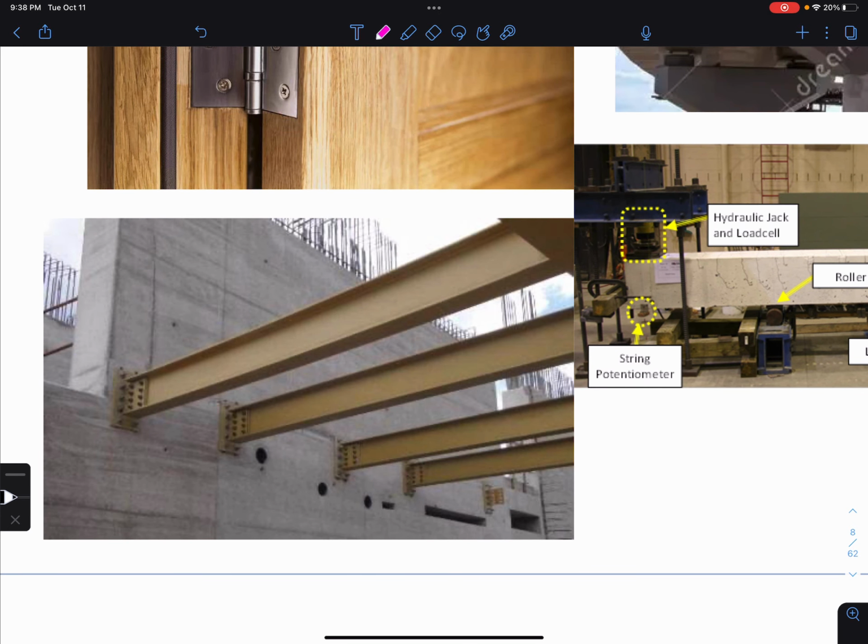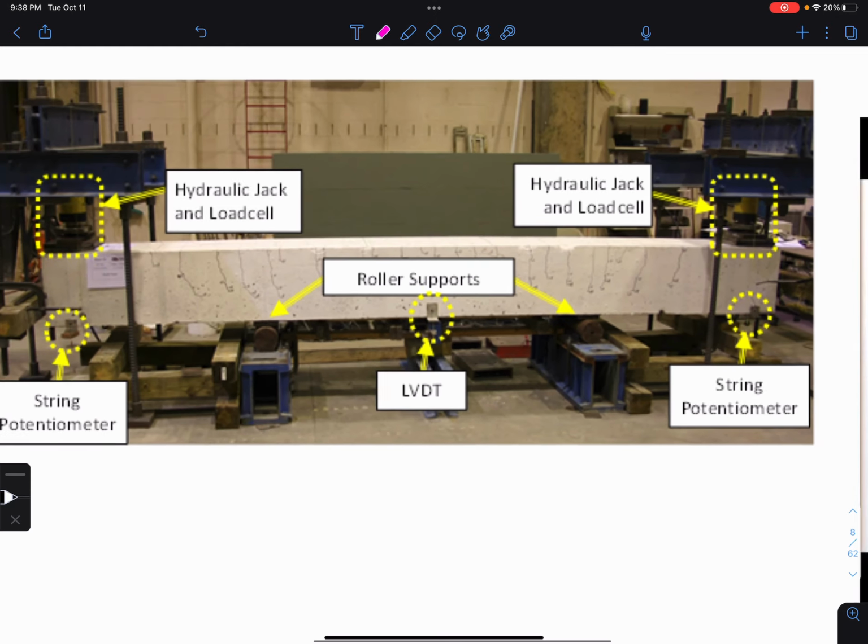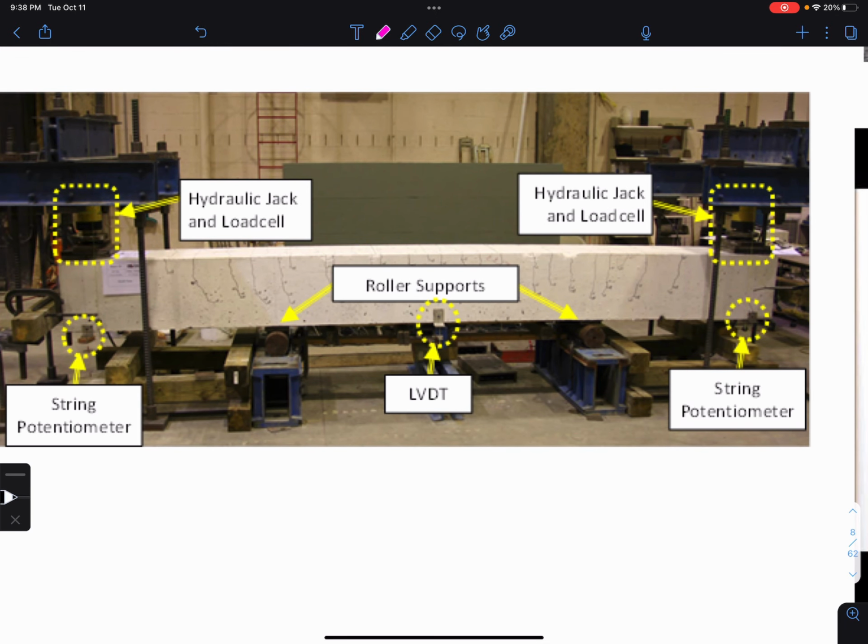These are steel beams framing into a concrete wall, and they're fixed, which means they're bolted basically. This is a fixed connection. They can't move up and down, they can't move left to right, and they can't rotate unless you were going to break the system. Okay. Here's an example of an experimental setup with a beam. The beam is supported by rollers. Okay. You see these two circular objects, and what a roller does is it provides vertical support, so you can't translate up and down, but you're allowed to translate side to side, and you're allowed to rotate.